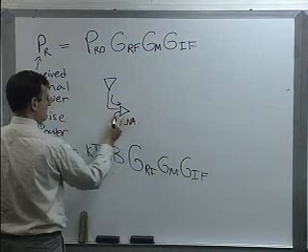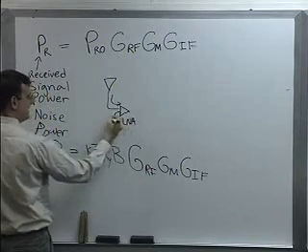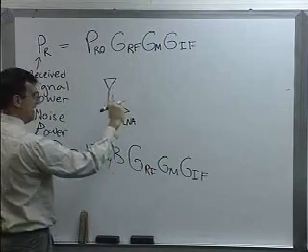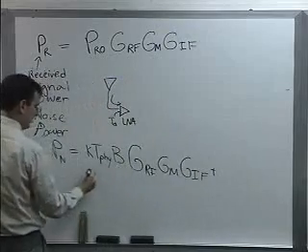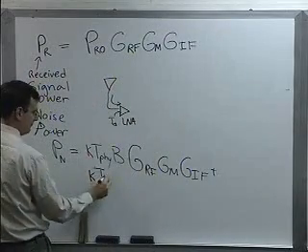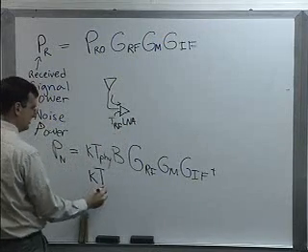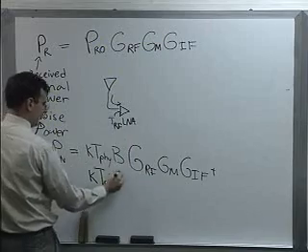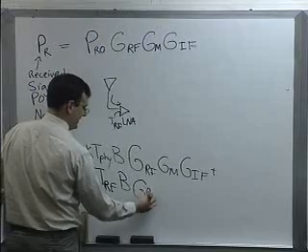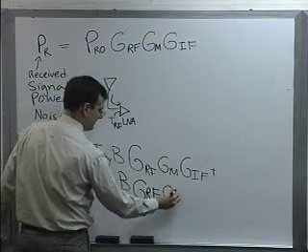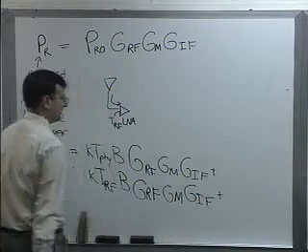And in our noise model, we take the physical noise of the device, add it in, and that's actually before it experiences the gain in our convention. And so added to this is going to be Boltzmann's constant times the physical device noise of that LNA, which in our previous diagram we called T sub RF. That's going to be multiplied by the bandwidth of our system, and it's going to experience the exact same gains that the physical noise experienced.